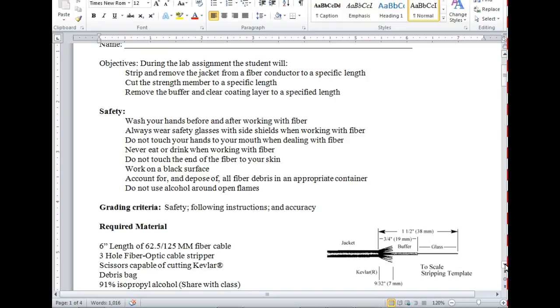So that means when we do these connectors and we do these splices, if you don't strip these right, it's a problem. With copper, we're okay. I always say, we don't want any insulation under the screw, and we don't want any wire exposed past the edge. That's pretty easy, so you've got a little leeway there on copper. When we crimp, we want the jacket to be inside, but it's not exactly how far it goes in there, as long as you're not crimping the connector on the insulator. But when we start getting into fiber, these lengths have got to be almost perfect.